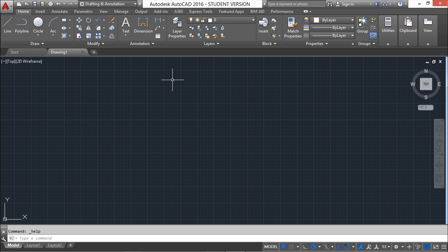I would like to show you also one functionality. Sometimes this ribbon bar is not shown, and we will see this area where I'm writing. We need probably to write ribbon if this is hidden for some particular reason, okay? In this area that we can call command line, if we write ribbon, then this ribbon will appear. So if you have problems, please take a note of this because it is important.